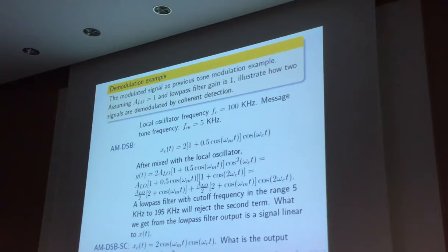If you view this delta omega as a carrier frequency, now actually you are modulating your message again. But this time, because delta omega is a very small frequency, although you modulate it, you still can tell the voice information. It's just that you will hear some whistle inside. This whistle is due to this term, because what you hear is this one multiplied by this one.